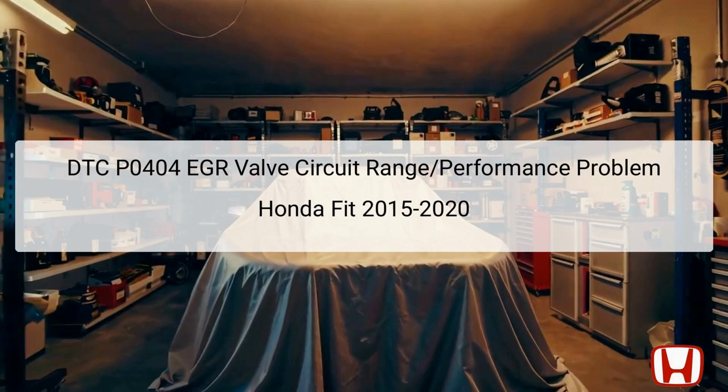The DTC P0404 indicates an EGR valve circuit range or performance problem. This code is specifically related to the exhaust gas recirculation (EGR) system, which is crucial for reducing nitrogen oxide emissions and enhancing fuel efficiency. The EGR system recirculates a portion of the exhaust gases back into the intake manifold, thereby lowering combustion temperatures. Problems in this circuit can affect vehicle performance, combustion efficiency, and emission levels.